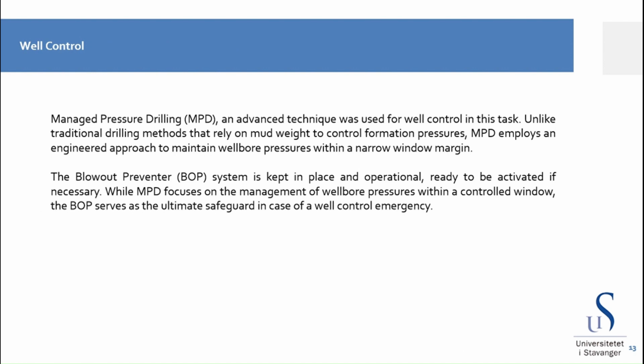For this task, we made use of the managed pressure drilling technique for our well control, which employs an engineered approach to maintain wellbore pressures within a narrow window margin, unlike traditional drilling methods that usually rely on mud weight to control formation pressures. The blowout preventer, that's BOP, is usually kept in place and operational, ready to be activated if necessary. The MPD, managed pressure drilling, focuses on the management of wellbore pressures within a controlled window, while the BOP, blowout preventer, serves as the ultimate safeguard in case of a well control emergency.